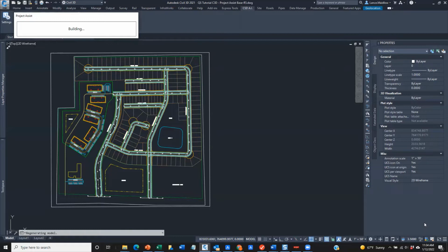Think of this as just your preliminary design as we go through this. It's saying, let's take the templates you've assigned, apply them to all the alignments, go through and do the cleanup at the curb returns. That's been computed and done. And remember, anything that's done at this point is just your preliminary design. It's not your final design. But it gets you to the point where you can get into your detailed design very, very quickly. Let's build out the cul-de-sac.